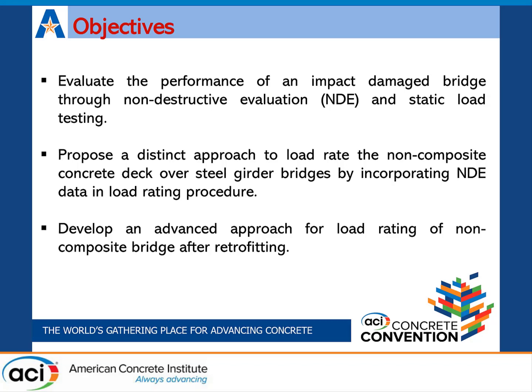The objective of this study is to evaluate the performance of an impact-damaged bridge through non-destructive evaluation and static load testing, propose a distinct approach to load rate the non-composite concrete deck over steel girders by incorporating NDE data in the load rating procedure, and develop an advanced approach to load rating of a non-composite bridge after retrofitting.